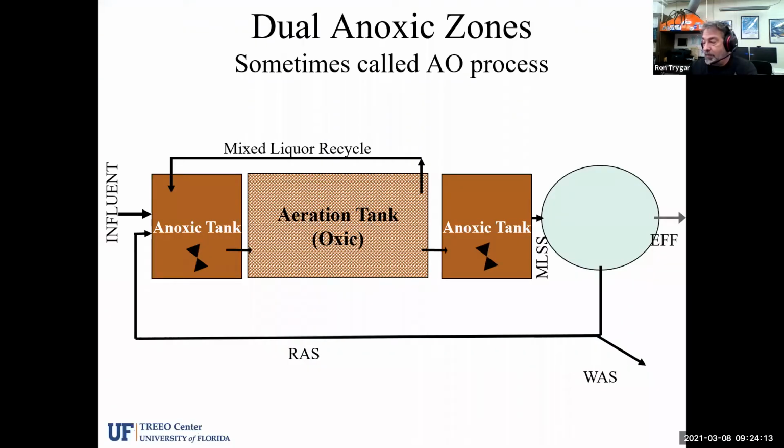All right, so let's say that we wanted to get lower numbers of nitrate or total nitrogen out of the facility. Let's say we want to convert more of the influent total nitrogen coming into the plant. Maybe we want to get it down even lower. So the influent comes into this first basin here as the pre-denitrification basin, like we had in the Ludzak-Ettinger process. So if you look at the way this flow pattern is right here, we have the MLE process, but then you also notice that in this case it goes like this.